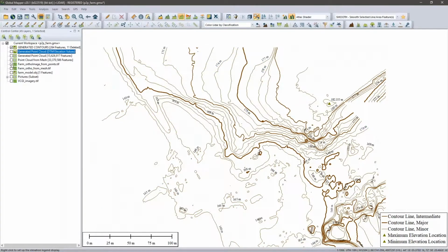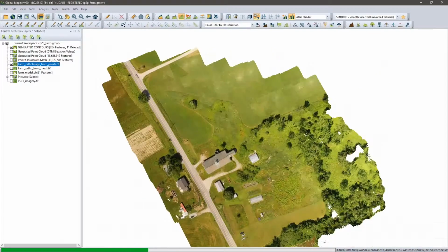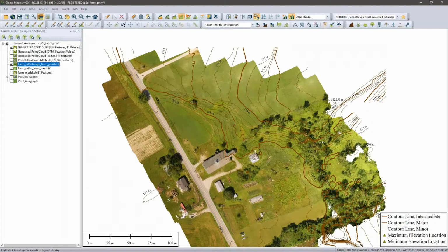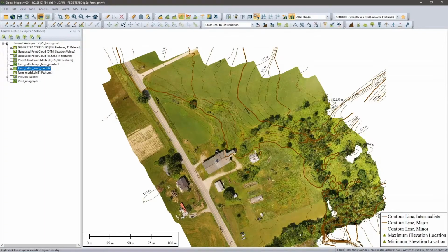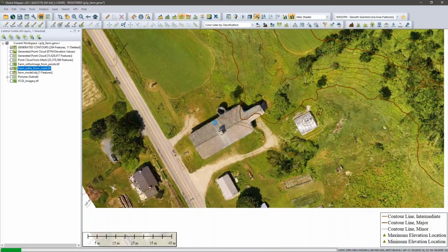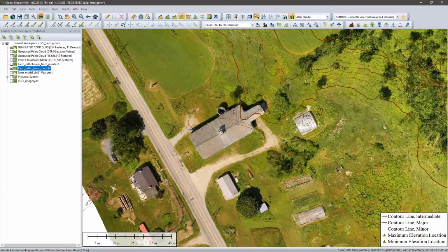So here's an ortho image generated from the point data, and then a slightly different version here that's going to fill in a few more holes, generated from the mesh surface. So we get a nice detailed ortho image here, pretty high resolution, of this farm site, just using that data, which originally had just an XYZ position. We can also even do it on photos that don't have the XYZ position to start with.